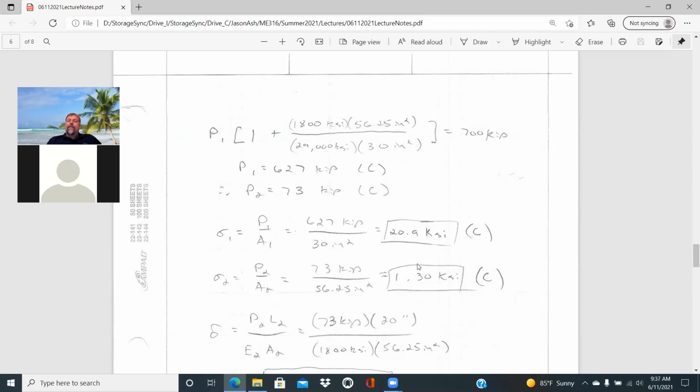And also just note that the magnitudes of these, in regard to failure and the factors of safety, are something you need to look at, because the yield or ultimate strength of one material might be much lower than the other. So even though steel is supporting more stress here, it may even have a higher factor of safety than the wood, just depending on its yield or ultimate strength.